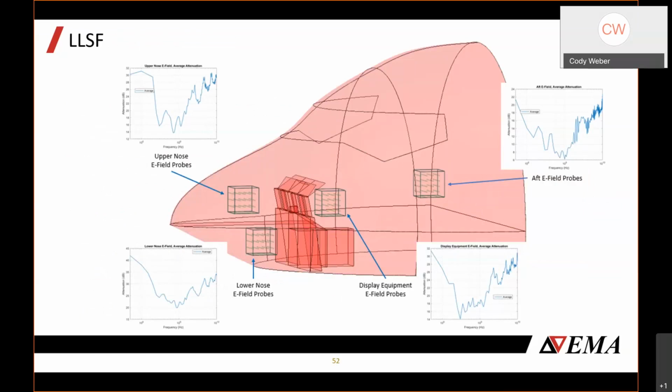And so of course, there are considerations and different types of models that you can build for this, but really, we think that using this subgrid, submodel approach and these box region probes, and using the average field analysis and 5% bandwidth averaging is very comparable to what is done during testing, and for other reasons I've mentioned throughout this presentation, can expand upon and create more value than what can be done by testing alone.